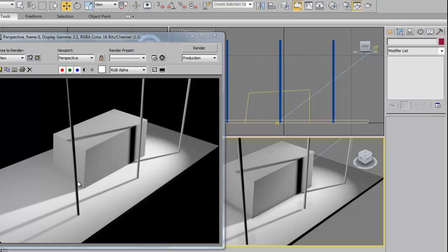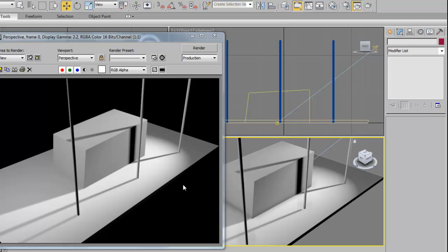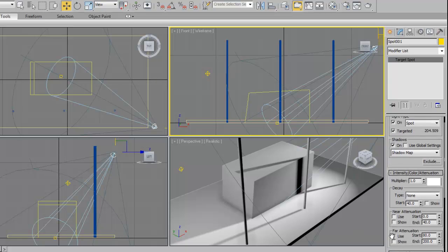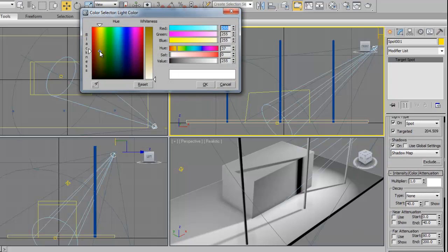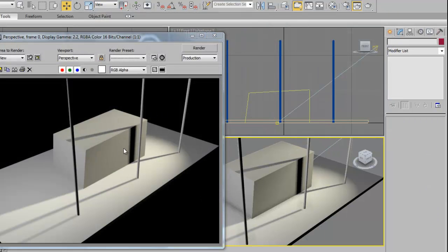I'm getting a bit of fill in my lights, but I'm still getting some shadows here. That's fantastic. Now, the last thing is this is still very monochromatic, and it is kind of unrealistic. So what I'm going to do is put in a little bit of color. If this were the sun, if this were an exterior setup in the northern hemisphere of our planet, it would be quite usual for this white light, this key light, the sun, to have maybe a little bit of yellow in it. So what I might do here is put in a tiny bit of yellow like that, just something faint. Don't go mad on it. Okay, that's a little bit green. So there we go. That's something like that. If I render that, then you can see it's got a little bit of, as photographers would call it, a little bit of flavor.